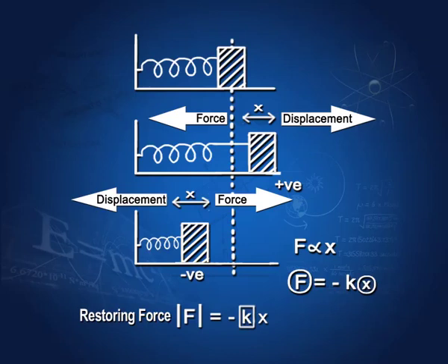Now, this quantity k is called the spring constant. The spring constant will depend upon how the spring is wound. That means, different springs are going to have different spring constants. I have got two springs over here, and I am going to suspend equal weights from them, and we are going to see, because of their spring constant, is there any difference in their extensions.